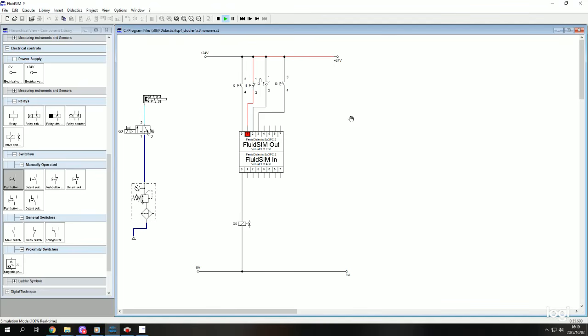Now we will move to exercise 3. So we have 2 push buttons, but we don't need a 5-2-way because both of these push buttons are for the same function, to advance our piston rod. If we were to use a 5-2-way without a spring return but with 2 points for our valve solenoids, then it would mean that this push button would be for advancing, the other would be for retracting. Actually, let us just, out of interest sake, test that out.